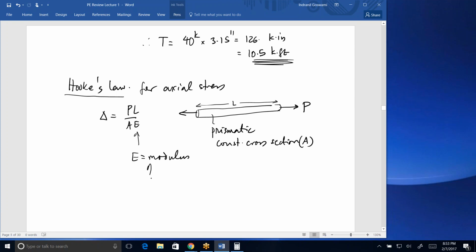The modulus of elasticity of structural steel, for most common grades of steel, is pretty constant. For steel, the default value is 29 million PSI or 29,000 KSI. So if they are talking about steel, they may just leave this out and say that's a well-known common value, not too much variation about that, so people will know that